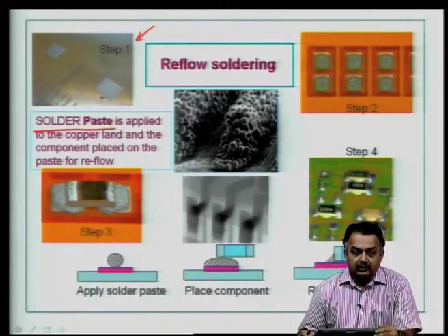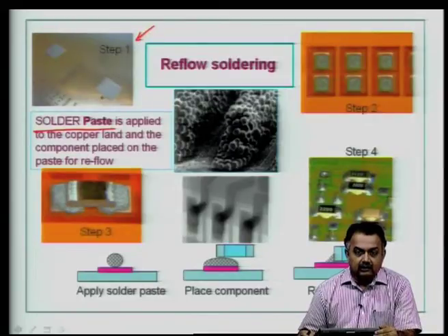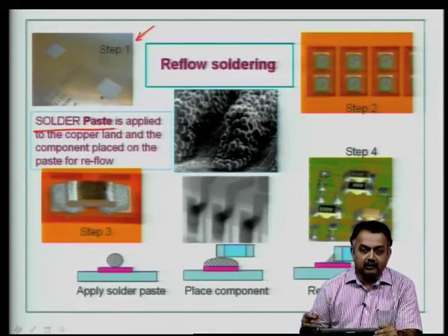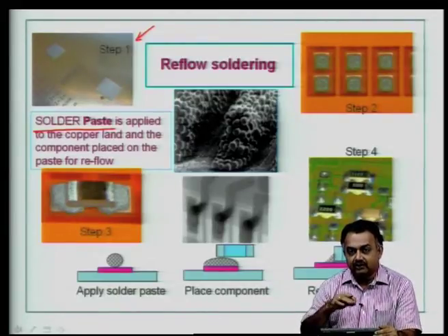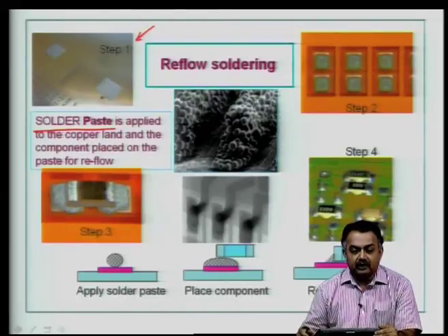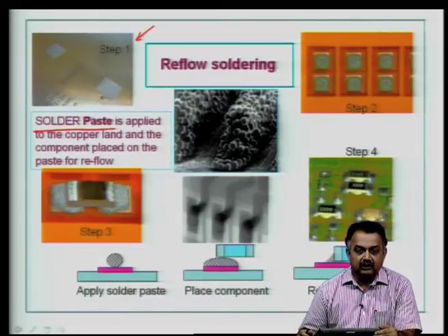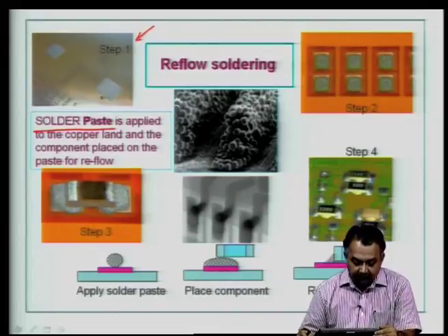Therefore, this is a very important material for the reflow soldering process compared to the wave soldering process, where you are depending on attachment of the through hole component through a large wave, which basically helps in wicking the solder through the component lead into the via and performing an interconnection process.